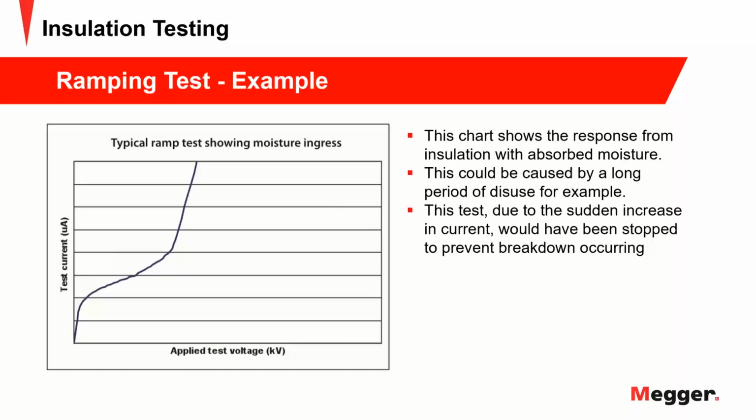So this is a good time to terminate the test. And if you look at your curve and the test results, you can get an idea, if you're familiar with all the particulars of this kind of test, and like I said, it's available in the literature, where the problem is in your insulation and what you might have to specifically deal with. Next.